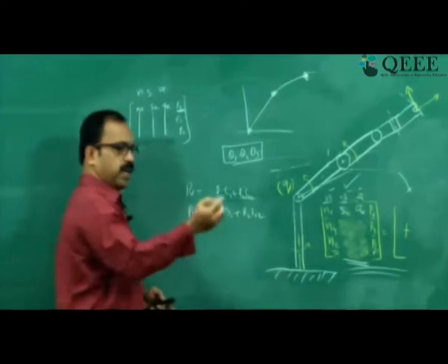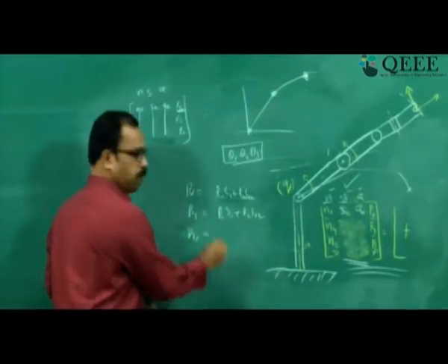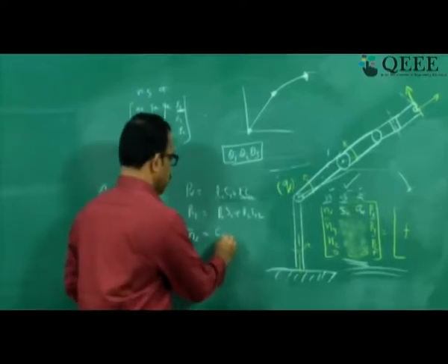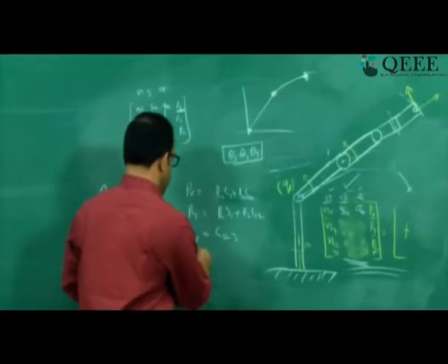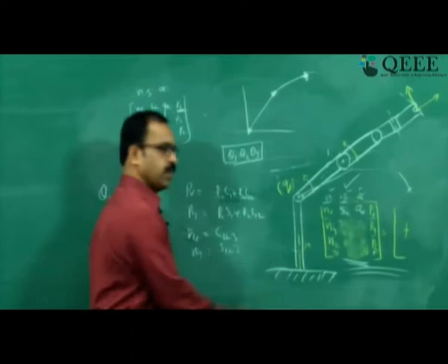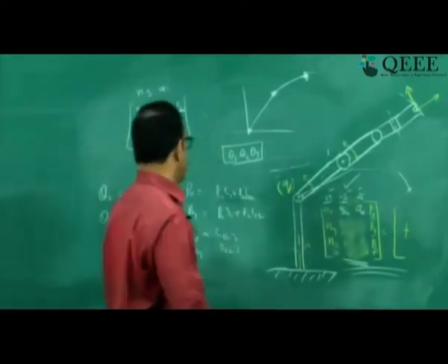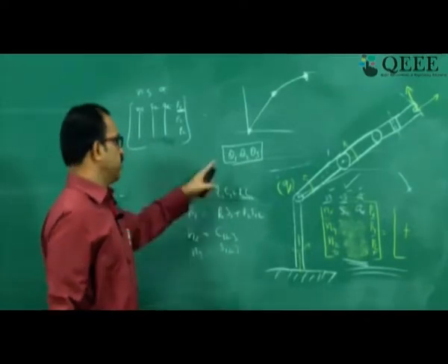Similarly, I can write all the others. Nx is equal to C123, cos of theta 1 plus theta 2 plus theta 3. Ny is equal to S123. So these are the equations, and from here I will be able to get 12 equations: 3 from Px, Py, Pz.